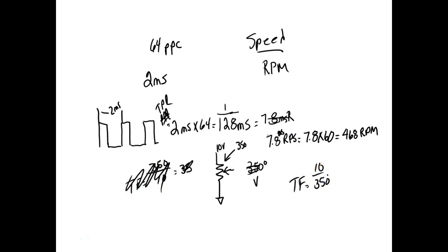Because what are we going to get out of these things? We have two things we normally get out of these sensors. What are the two things we get out? Volts or current. Volts or amps. So this is going to be milliamps over something, or volts over something, and it all depends on how we set the span of the pot, right? And then we get our transfer function.